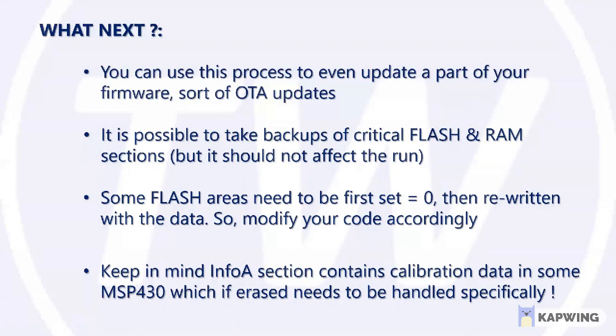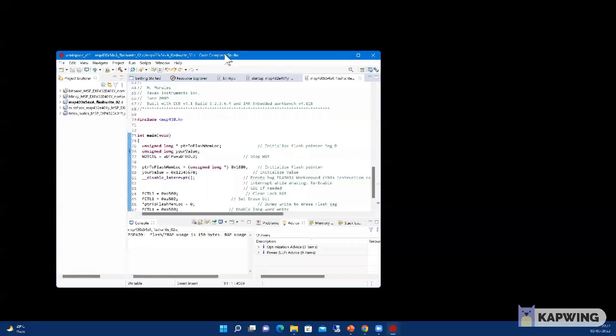So if you erase that, you will have to go through a detailed factory programming procedure described on the Texas Instruments website in order to get them back. So it's better to consult the device datasheet and the user guide, and then go into the system. Okay, so now I will just show you a very small demo.